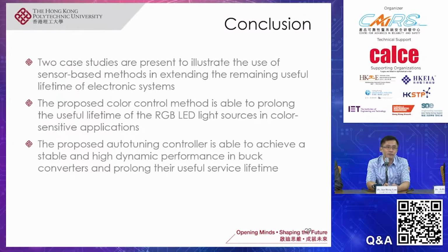And the second example is we've also presented an auto-tuning controller, which is able to achieve a stable and consistently high dynamic performance of a buck converter despite significant change in the inductance and the capacitance values. And as a result, we're able to prolong the useful lifetime of a buck converter.